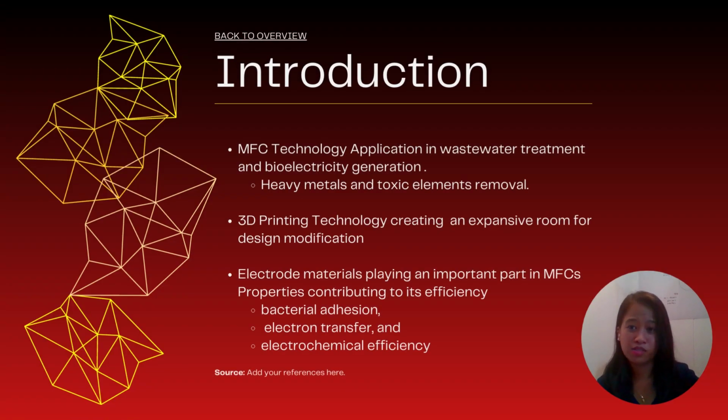Microbial fuel cell technology has increasingly become a topic of prospect because of its application in wastewater treatment and bioelectricity generation. Our study centers on the application of 3D printing in the design and assembly of the microbial fuel cell system. Here we created a 32 solid MFC system, which is quite a leap from the usual number of existing assemblies of 7 to 15 cells.